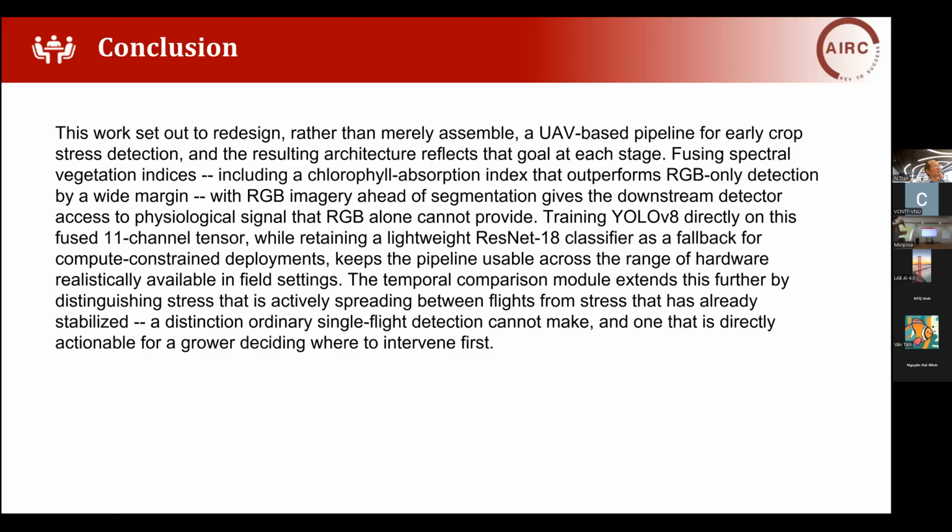Why? Okay, so for using YOLO V8, the minuscule amount of detection and the weeds can be very tiny across a huge 300 meters of data. To properly detect that and not miss it during the speed of UAV travel, YOLO V8 is a better option currently right now. Because when we're working with the UAV, we have to make a compact or light deep learning model, so we can run in a very fast, real-time system.